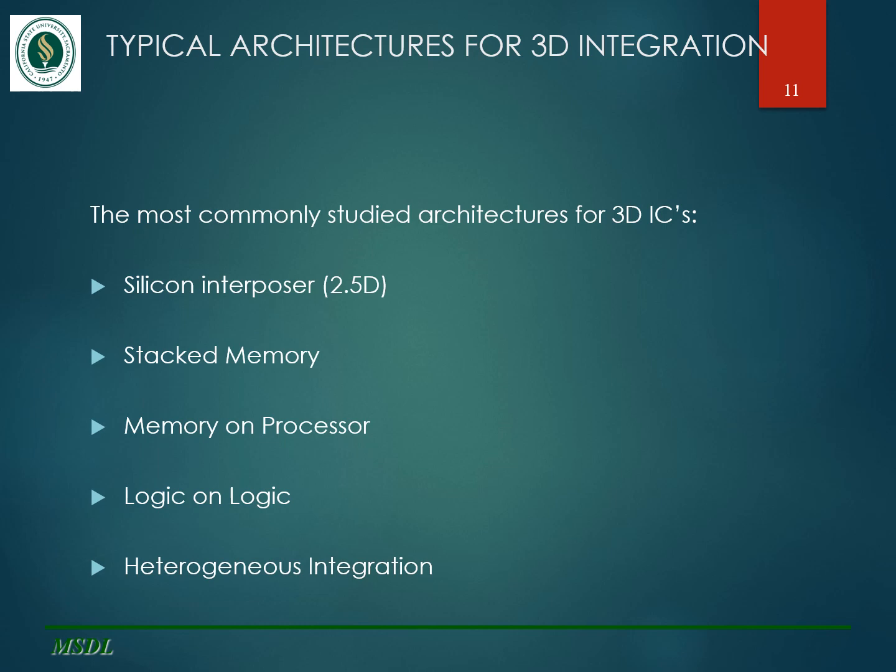Heterogeneous integration. This is the ultimate holy grail for researchers seeking to integrate multiple technologies stacked together in a single package. The dream is to one day combine logic, memory, RF, sensors, ICs, built separately in an optimal technology, within a package. There are several advantages to such heterogeneous 3D ICs, including cost, form factor, performance, IO connect reductions, and lower power consumption.